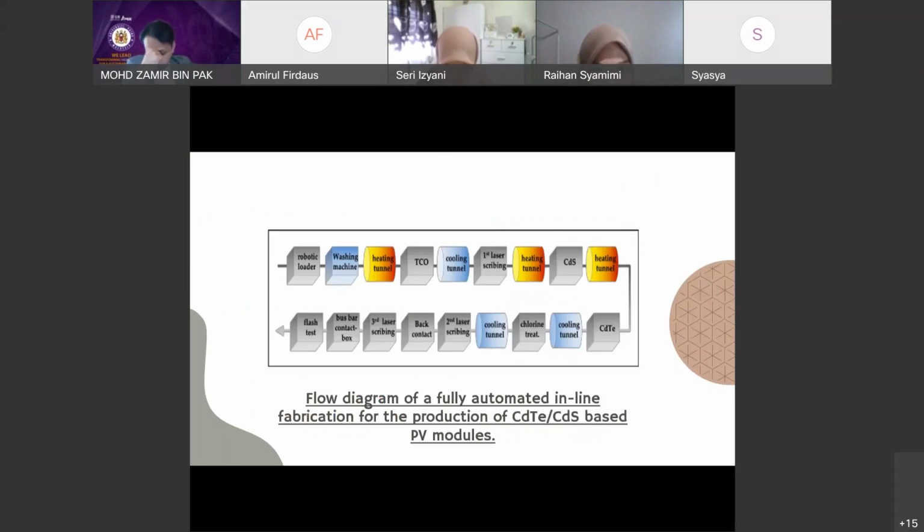It's like annealing, to remove residue or oxide on the surface to make it less defect and more conductive. Okay, so the effect is pretty much like annealing, but if you look at the 3 different heating tunnel steps, they are actually unique depending on the step.